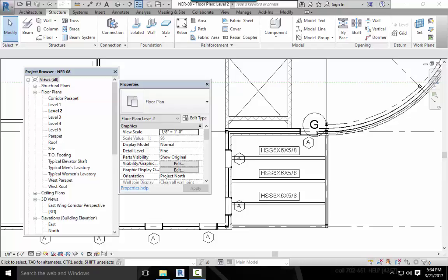And in this one, we're going to add a thin rod to the top of the canopy. It would be nice to add a rod to the top of the canopy at an angle. You can accomplish this by using the brace command. To do so, you'll need to load the rod, considered a family in Revit, into the model. To use the brace command, first add the rod family to your model.